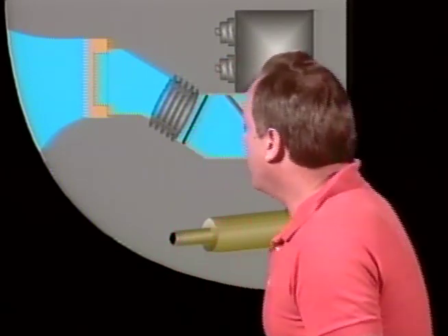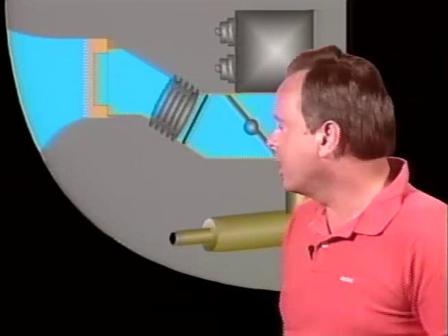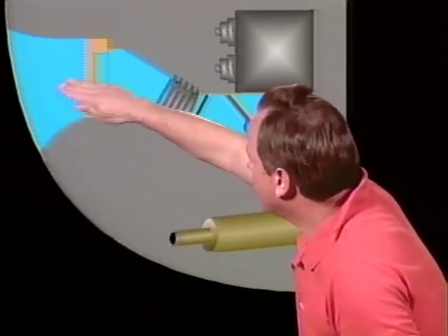Now, let's assume you want to start this engine and it's equipped with a carburetor air heater. Should you start the engine with a carburetor heat in a hot or cold position? Well, the answer is anytime you're operating on the ground, you want the carburetor heat in the cold position so that you have filtered air going to the engine. Otherwise, the air is unfiltered. So you start the engine, operate it on the ground with the carburetor heat in the cold position.